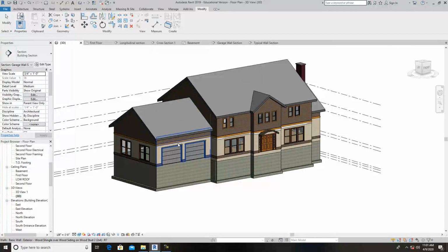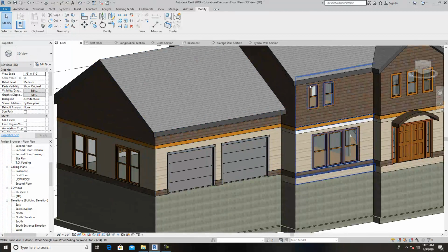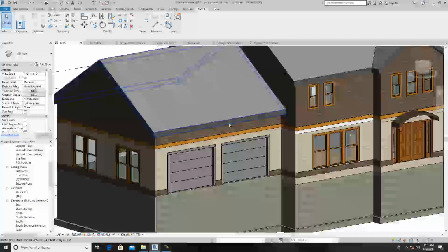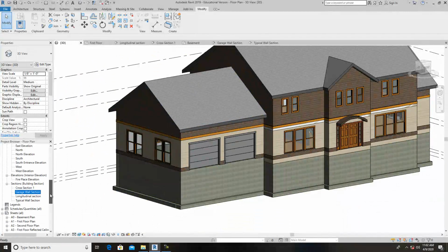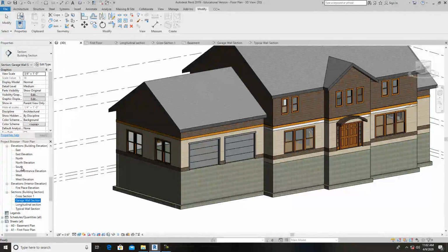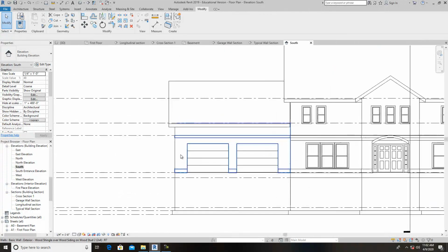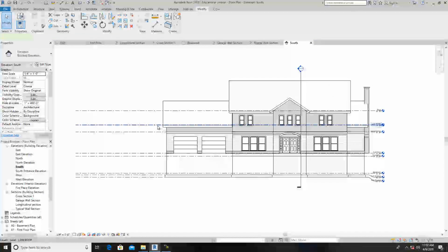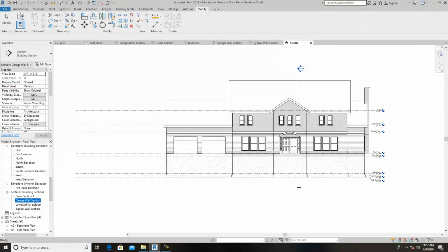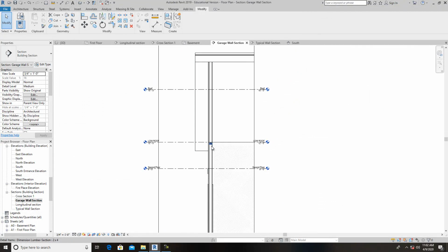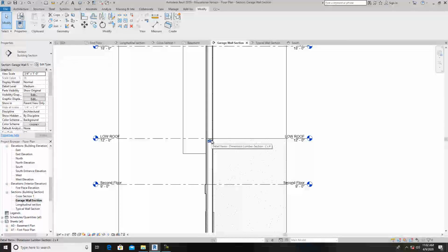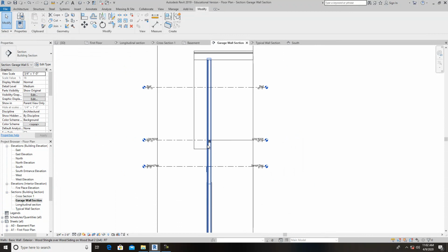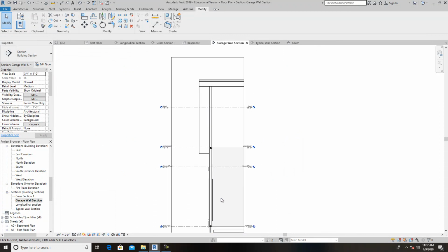Okay. Yeah, you're wanting to go to that. I want to go to my elevations, but by looking at that just real quick, it looks to me that the roof is setting on the low roof, so that's perfect. We'll take that section all the way up to the low roof and put our double plates right here. That's where the roof is going to be setting on. So we're in good shape there.